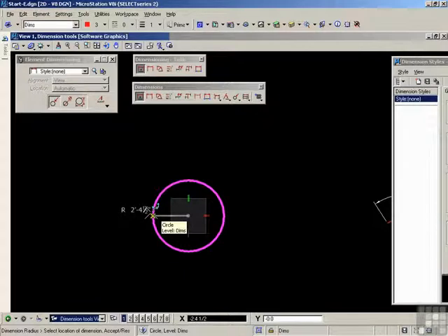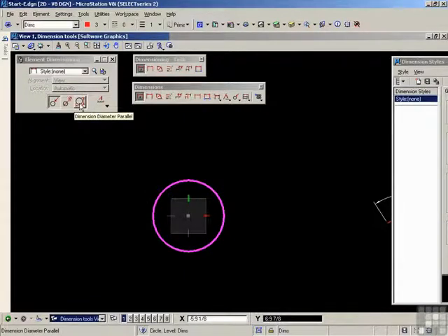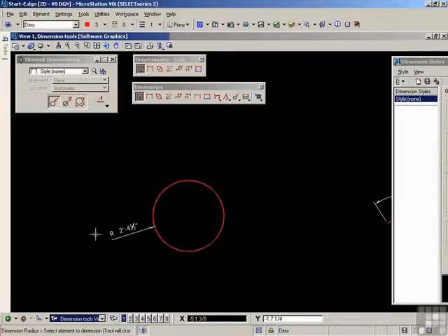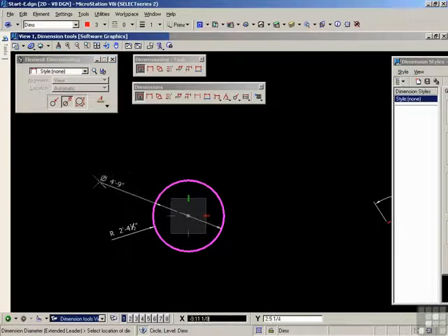And notice that immediately in the tool settings window, the actual options change, and they are actually displaying radial dimensions. This is so because we selected a circle. MicroStation knows that and has changed the tool options for us. We'll stick with the first one, dimension radius, and we immediately see that the radius is popping into place. And this is essentially exactly the same as the first tool on the radial toolbox. Let's try the second one, which is dimension diameter with an extended leader. So this is an extended diameter setting, again, as we saw before.